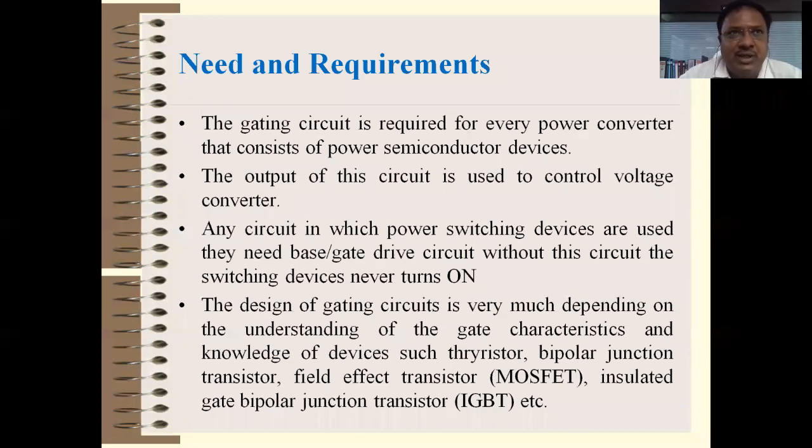Many times it happens that the SCR, which works on very high power rating, may get damaged, and due to that a large heavy current may flow through the gate towards the drive circuit. And if it happens, then definitely your drive circuits may be damaged permanently. So it happens many times.